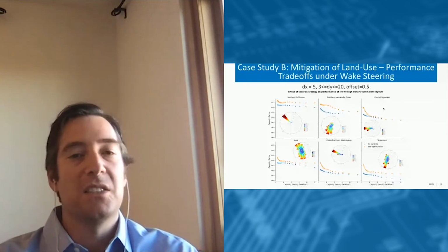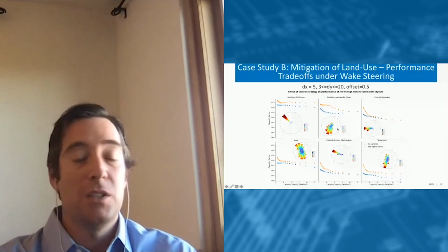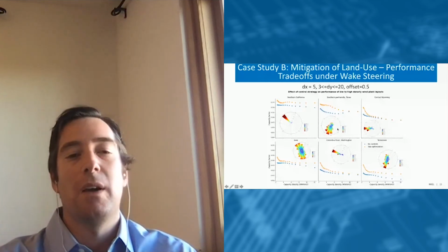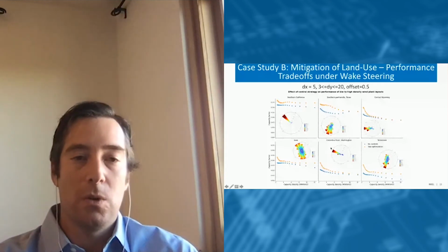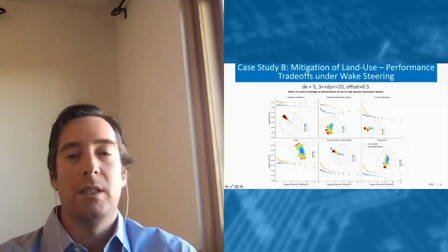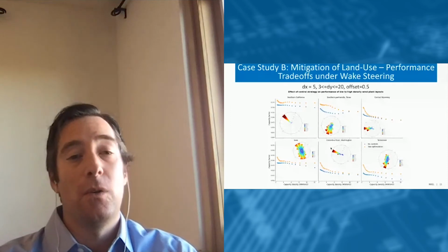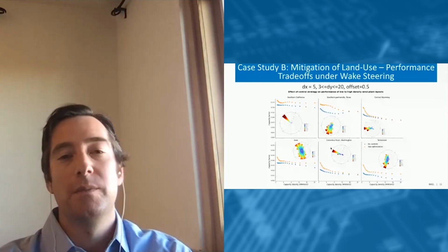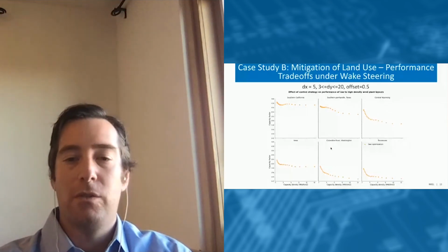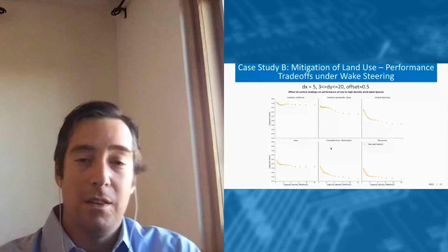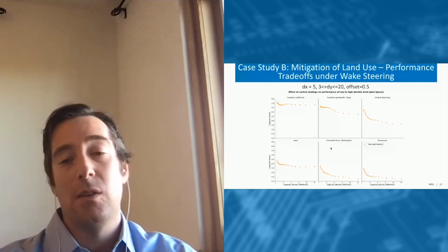Here we focus on 6 sites across the country. You can see the wind resource is variable for each of these locations as shown by the wind roses. In all cases though, the yaw optimization controls improve performance in that we see that there's less of a gradient as we increase the density and therefore land use efficiency of these wind plants. So quickly, if we focus only on this trade-off curve for yaw optimization, the beauty of the surrogate modeling approach is that we can then take this analysis and apply it to the whole country.